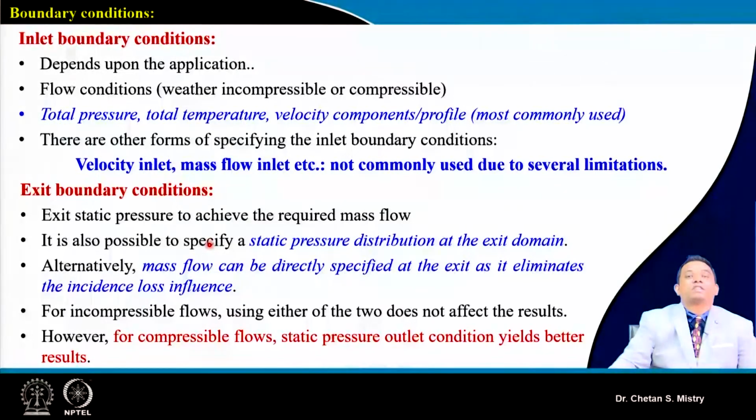You need to say this is my inlet, and at the inlet we need to put certain flow parameters. So based on what kind of application we have, we need to give my inlet boundary condition. So flow conditions basically: is it compressible flow or incompressible flow, you know better now.